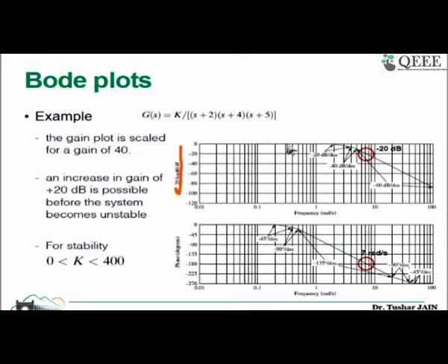Regarding this, before starting the Nyquist plot, let's take a couple of queries. The first asks: what is the relationship between stability and the coefficients of the characteristic polynomial? We have seen this while writing the Routh table, because we have the conditions there, which are functions of the coefficients of the characteristic polynomial. From there only you can get the conditions to guarantee the stability of your system.